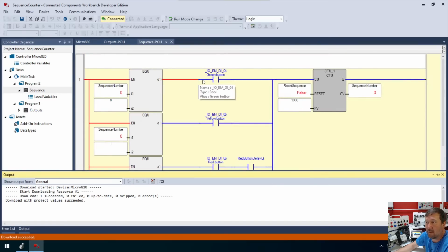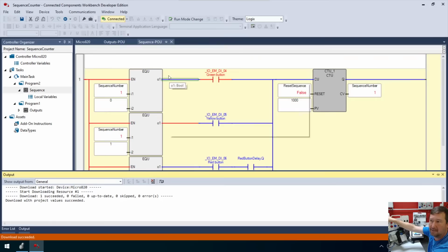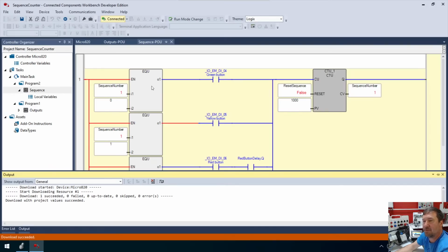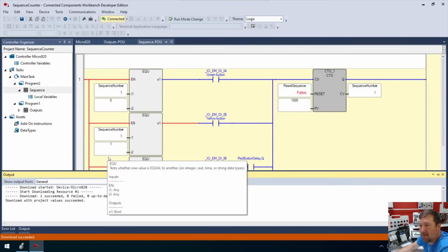This is the only true branch we have, so we press the green button, and you never actually see it go true there, do you? You saw that really this turned red, and all of a sudden this was blue. Well, that's because the scan cycle for that one split, maybe a 2-3 millisecond scan, I'm not even sure what the scanning time of this is, that was true. But our PC is not going to update that fast. So now we're in step 1.